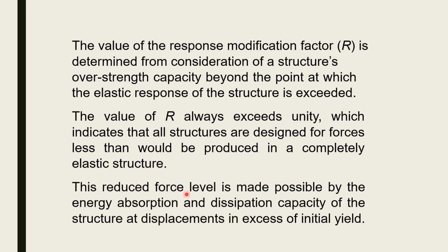This reduced force level is made possible by the energy dissipation capacity of the structure at displacements in excess of initial yield. After yielding, there are a lot of deformations. So this deformation will cover energy absorption and energy dissipation. So the response modification factor will cover all these things: energy dissipation and energy absorption after the yield.